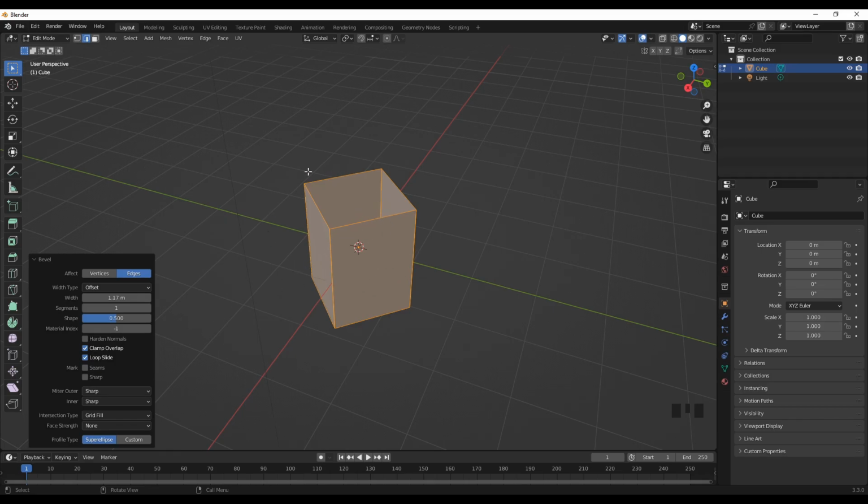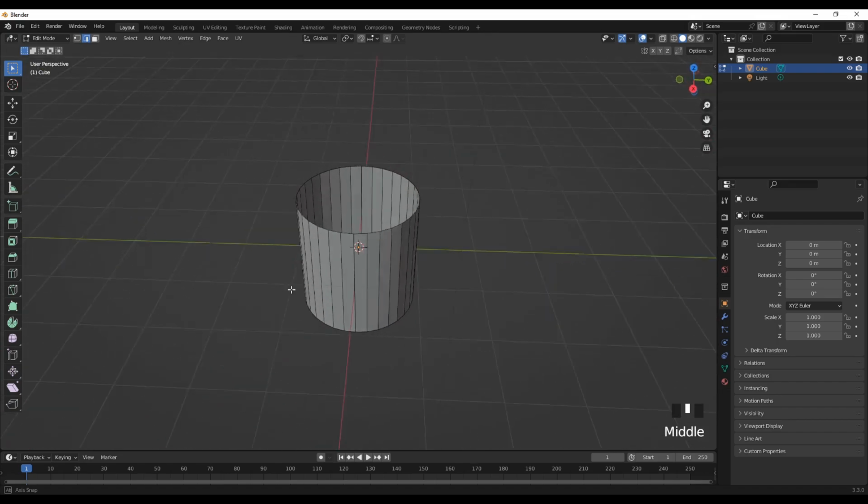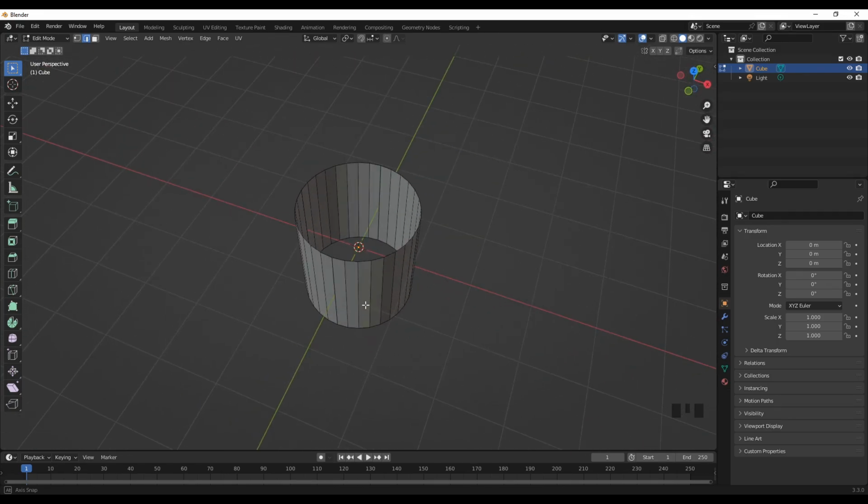The next part is, the pane structure is mostly cylindrical shaped. To achieve that, we need to increase the segment number like this. The more segments you add, the more perfect the circle appears to be. Okay, so I'll leave it at 8 for now. So the first part is done successfully. Now we have our starting point for the pane structure.